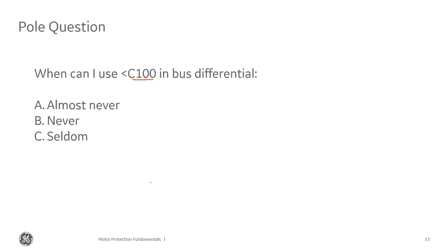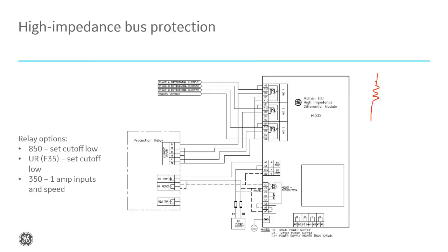And that resistor is going to pass some current. And the thing we know about resistors is they're going to generate heat. They're basically heaters. So we need to be able to protect that resistor. There are two things that protect that resistor. There is a MOV. So this here, pretend that's an MOV. The other thing that protects that resistor is some bypass contacts. And these are those bypass contacts here.